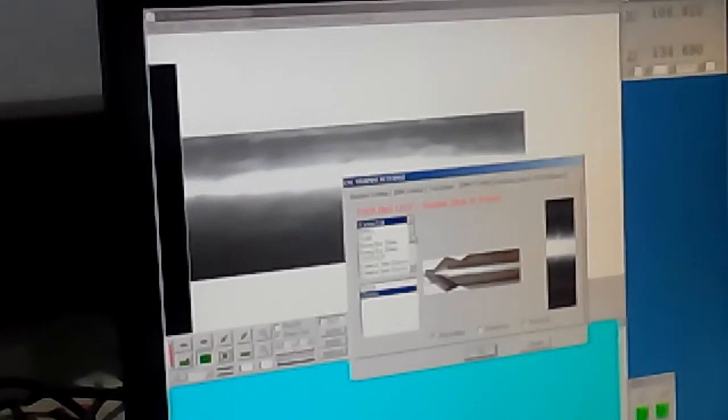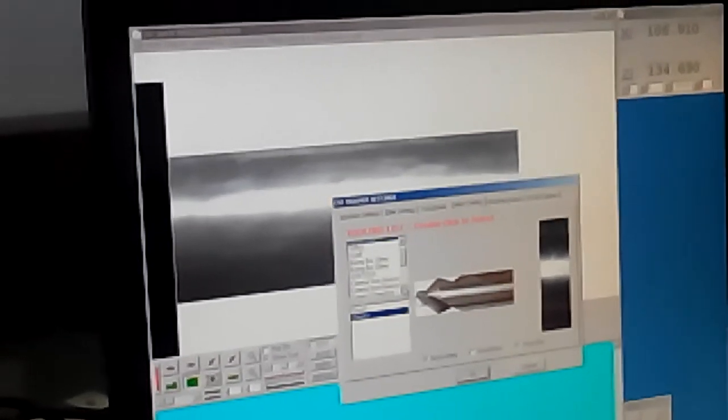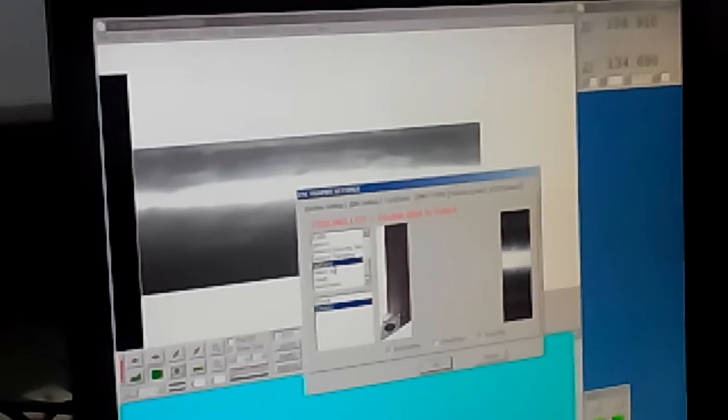Then you go again to Job Tooling and select Tooling. We are going to use the left hand tool, so scroll it down. You have the left hand tool and you can see this picture here. Go to the tool offset. In this particular machine, my tool number 5 is left hand. So I will go there, click left hand, and you can see it is already there. Add to tool library, I will add. So tool 5, left hand, you got it here.